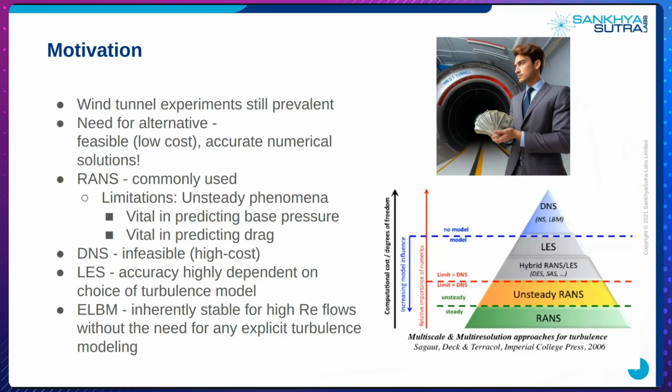In the industry, RANS is probably the most commonly used solution for this particular problem, as it gives you quick solutions and the macro features are captured quite well for most geometries. But it certainly has its limitations, in the sense that it can't capture unsteady phenomena as it's a steady state methodology. And as I spoke about in the previous slides, capturing unsteady phenomena is quite important to capture the flow features of any automotive geometry, as it's vital in predicting the base pressure, which is the pressure in the wake region, and therefore is also vital in predicting the drag force.